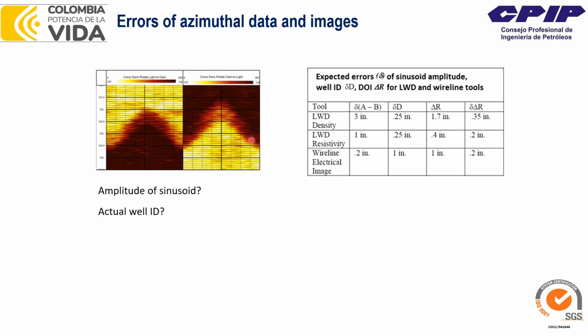So we have some variations, and to calculate exactly what the diameter of the borehole is at the current point, we would need to have a caliper, ultrasonic caliper, or some other sort of caliper to understand what it is exactly. But when we put the diameter of the bit, of course we make some assumption, okay, and this also affects the accuracy of the dip we calculate at the end.